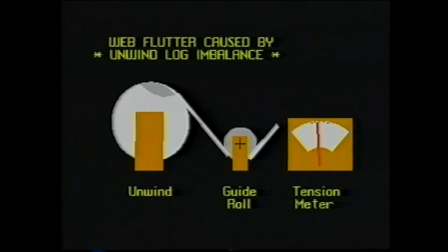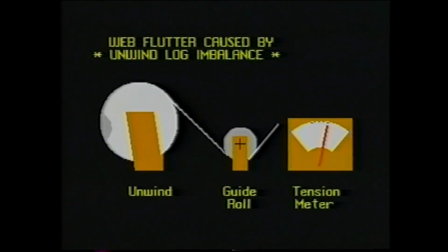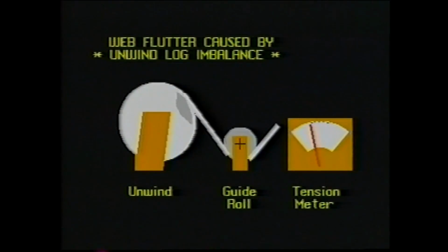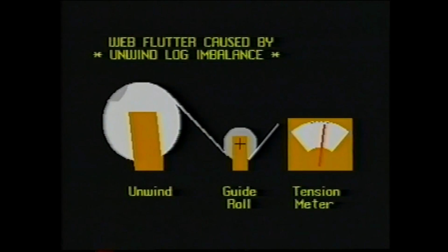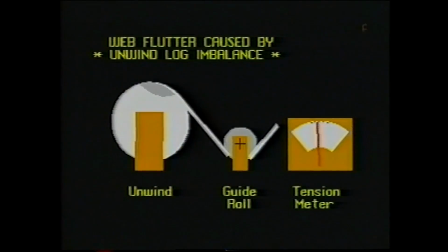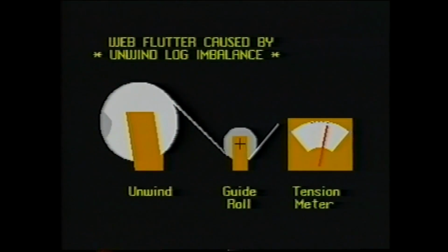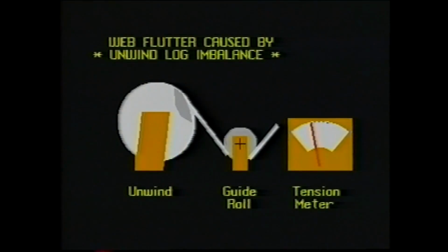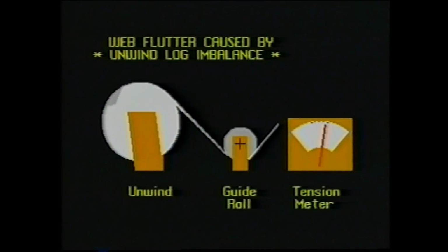Reducing unwind vibration can be accomplished by winding well-structured reels onto spools which are balanced and have good journals. Additionally, the unwind system must be stiff, with the reel spools held securely in rugged stands and supported by a substantial foundation. However, as we will see in the next animation, stable unwind stands are necessary, but not sufficient to provide stable web runs.